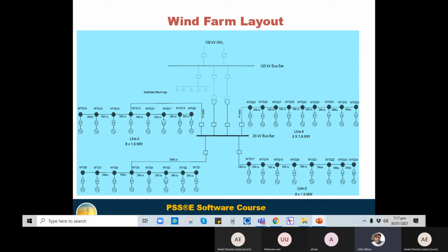In this way, you can see what information is required. The first information is the distance from this collector group to this one, meaning the cable. Similarly, the LV transformer: if one transformer has a certain MVA, we will multiply it by 8 and model it as one transformer here and one generator here, 8 times 1.5, like 12 megawatt, and then 12 megawatt here, 12 megawatt here, and 14 megawatt here, which will step up to the HV level.